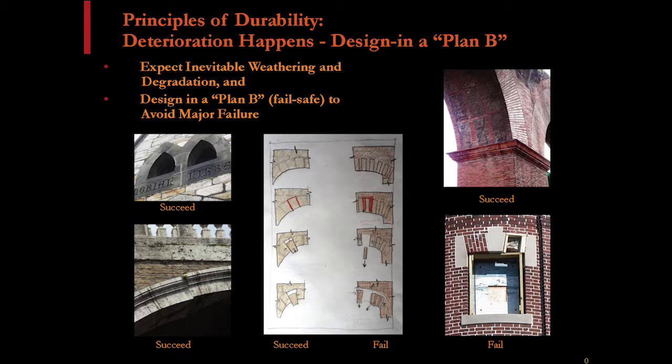He said he'd never seen brick fall out of an arch in the 30 years or so he had been doing masonry. And I think what was happening here was they had a very wide mortar joint, and the brick were not cut to wedge shapes. So when you lost the mortar, that brick was able to drop straight out, and then all of a sudden you had localized instabilities around it, and those brick were able to start dropping out too. And he had shored it with 2-bys by the time I got there, before a progressive collapse occurred.